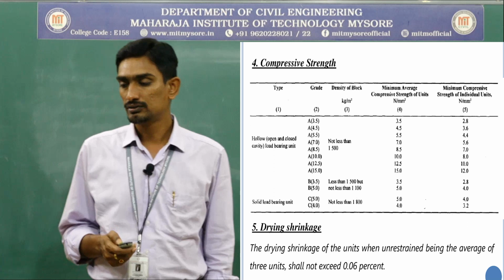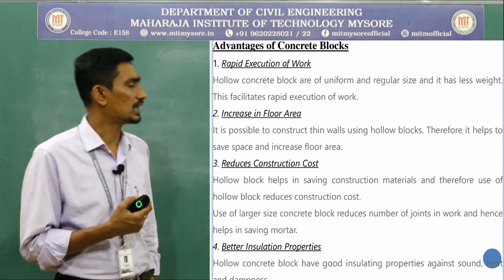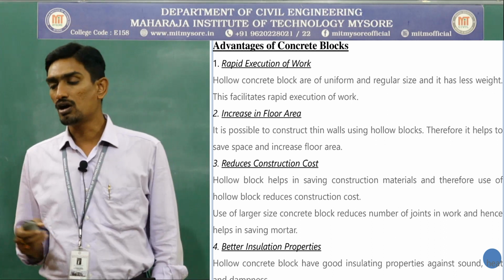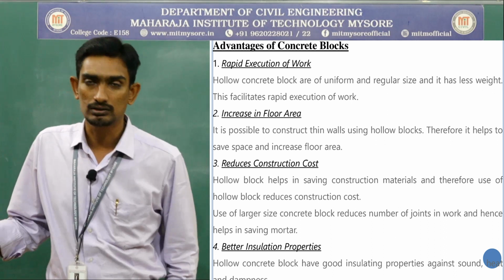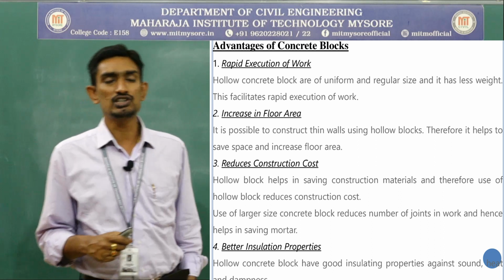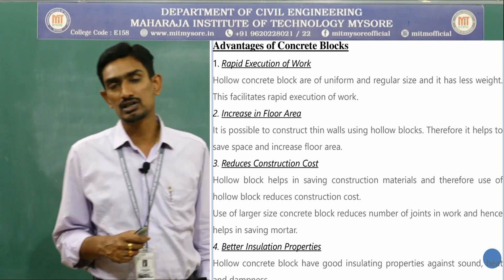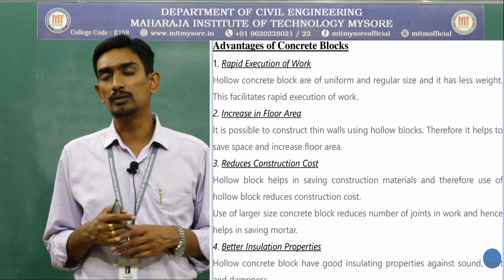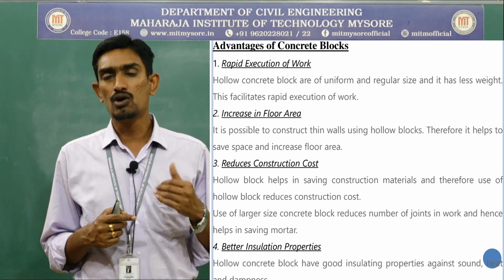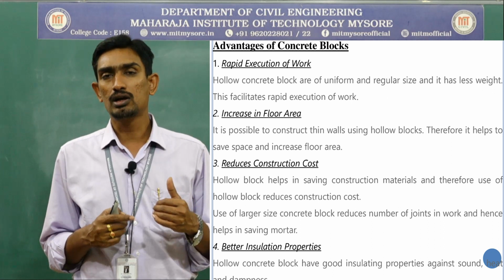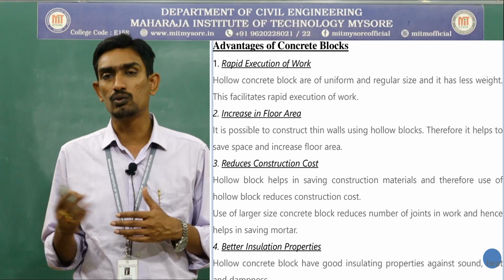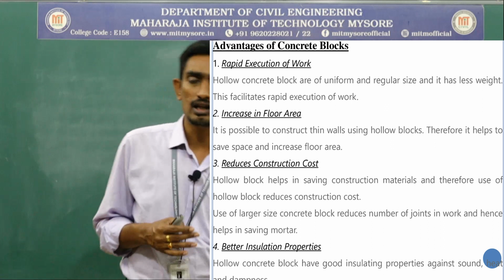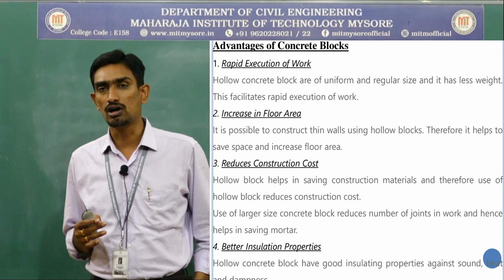Okay. So coming to the next slide, that is advantages. What are all the advantages of concrete block? So the advantage of concrete block is rapid execution of work. That means we can finish off the construction of a wall very fast compared to the burnt clay bricks. Why? Because the size of the concrete block is big. That means if you want to construct a 1.5 brick wall, by that time we can construct one brick wall or one concrete block wall itself. So that is the scenario. That's why rapidly we can construct the wall using concrete block.